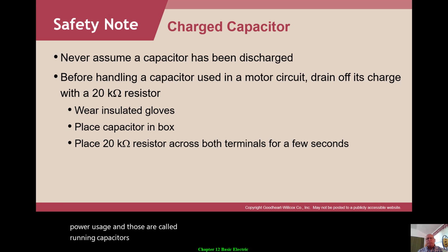So never assume a capacitor's charge, because it will hold a charge just like a battery, and so it can give you a nasty shock.